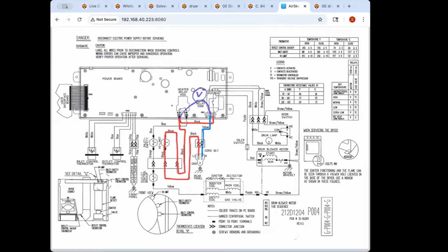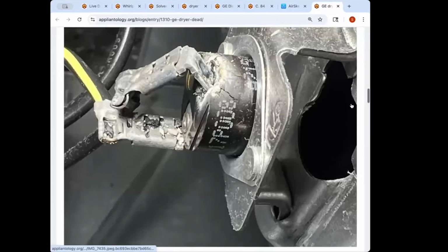Yeah. So on this one, did the thermostat fail of its own volition? There wasn't something else that caused it? Not that the guy said in the post, so we don't know. And keep in mind what you saw in Tim's pictures, how it was all burned up. In this case it's passing L1, it's just a gas burner, but you'll have some that are electric, where you're passing L1 current through for an electric heating element. Well, that's significantly more amps, and it's those amps passing through it that can burn it up.